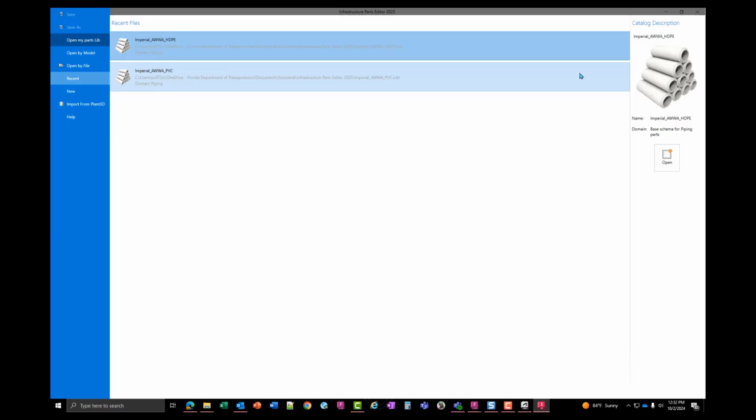So if you have a drainage network that's created with our old Part Builder parts, you can't then use our new parts, Inventor parts, in the same drainage network. That does not work. So we understand that you're going to have legacy projects when we do release our new parts. After we thoroughly test them, there's no time frame on when we're going to be done and ready. But we're going to probably rename our FDOT drainage parts list to let you know which one's Part Builder and which one is done in Inventor and Parts Editor.